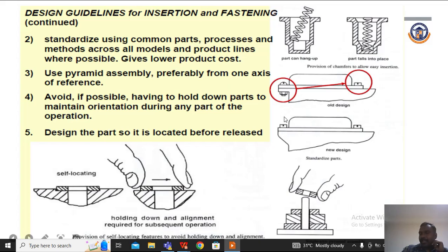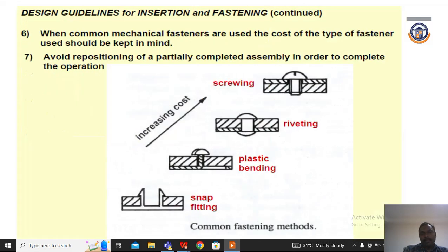That is a self fastener, and this one will be a bolt and nut. This bottom nut is difficult to assemble for the particular component. The countersink and then counterbore will have to be produced to easily assemble the internal sections of the product. And you can see that the type of fit will increase the cost.